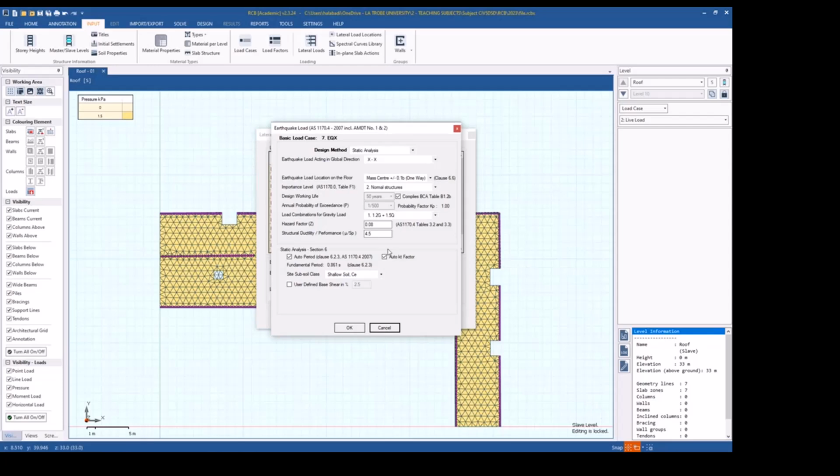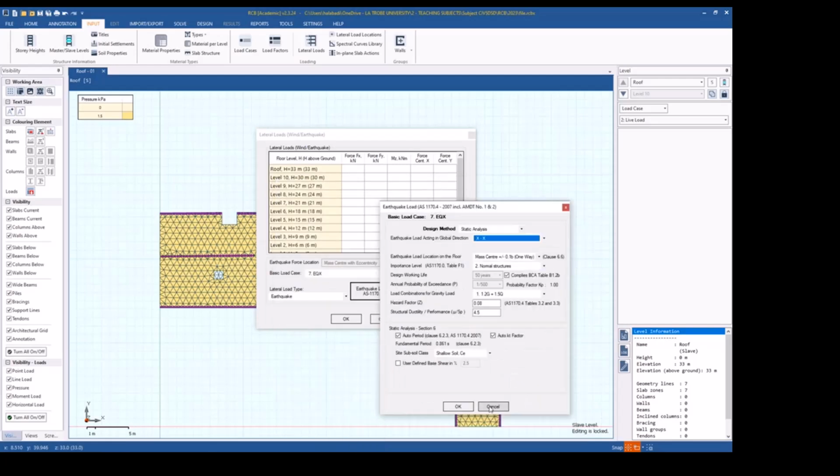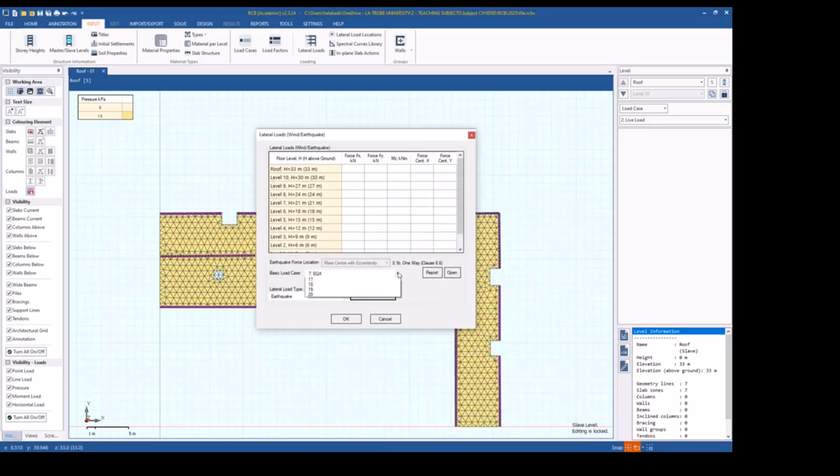Now, I just wanted to check if the software can automatically select the 30%. No, it's not. I thought it was actually going to consider the 30% on its own, but it seems not to be doing this. So you actually have to do it. Let me cancel so we don't get confused. You have to define another two cases, which are 0.3x and 0.3y.